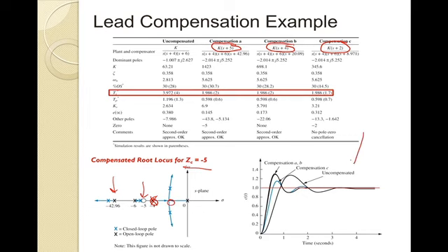And then the summary graphically here is a step response. What you'll see, relative first to the uncompensated system here in black, is that it's the slowest of the cases that we looked at. The compensated cases have a faster settling time, and remember our goal was a factor of 2.